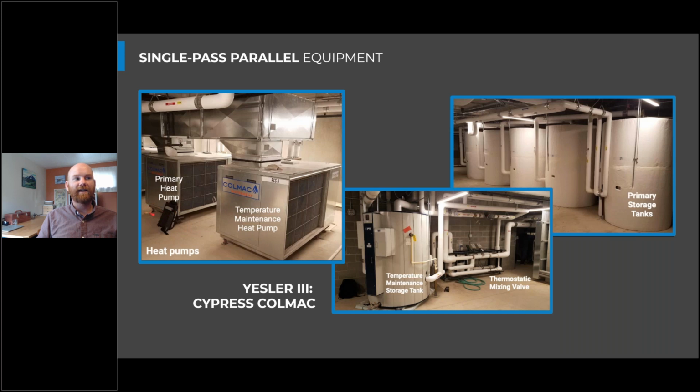So we would have had to increase the amount of them to address that lower efficiency. So this is really a great way to match these heat pumps to the load to get the most bang for your buck out of these, or when you're working with a larger commercial building with a large distribution piping network.